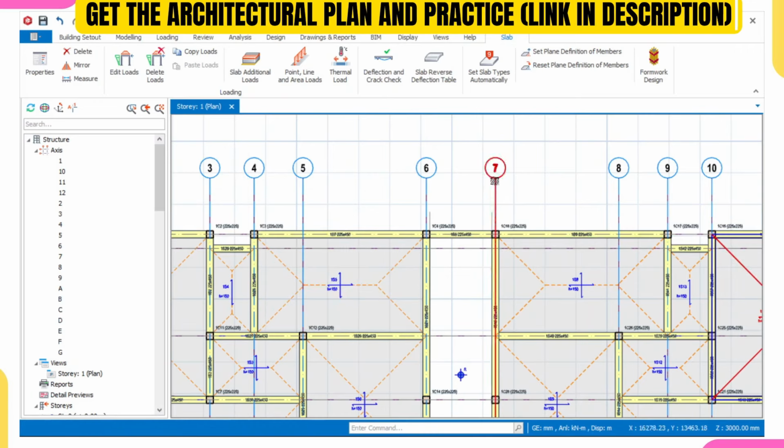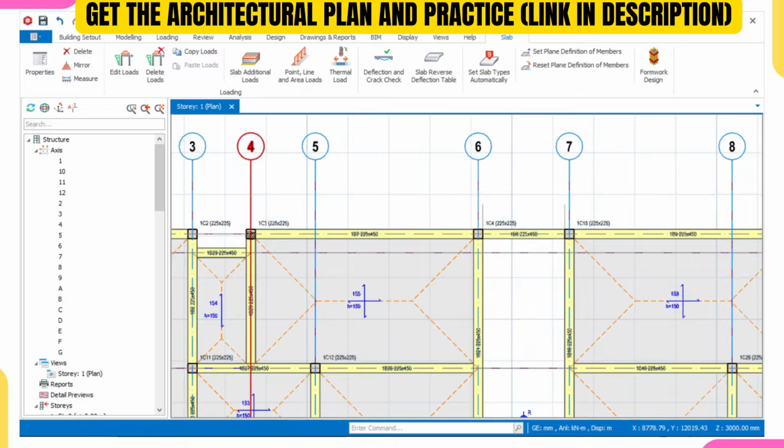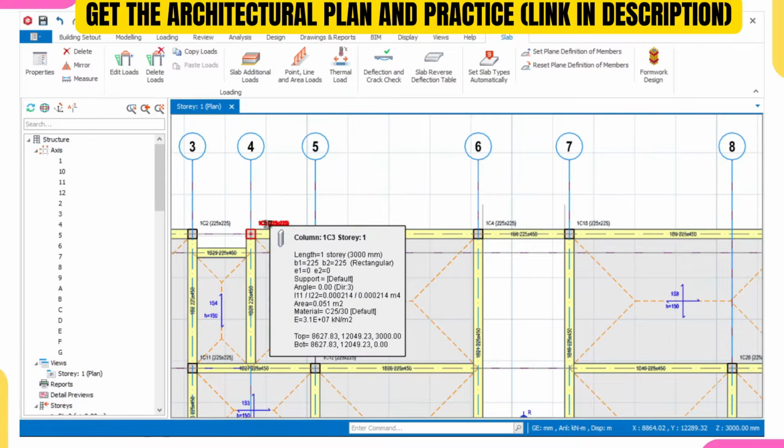It will come down, go up because of this hogging moment, come down because of the sagging moment, then terminate at this. Yes, so if you see now, it started from here because the moment at this point is 0. That is the reason why we should hinge here, because if you do not hinge here, ProtaStructure will not know that the moment here is 0.